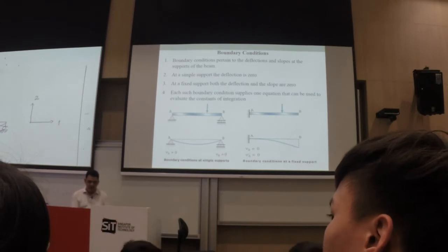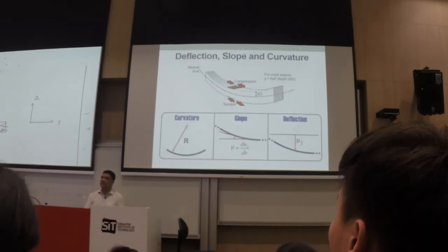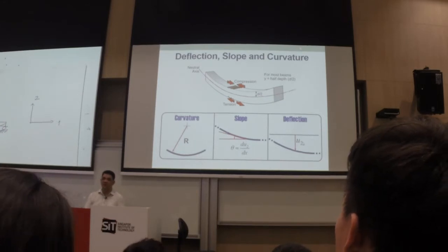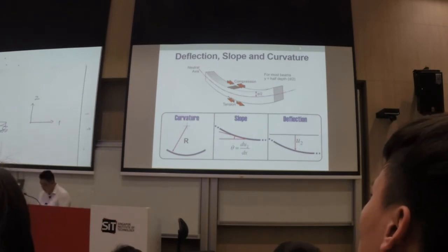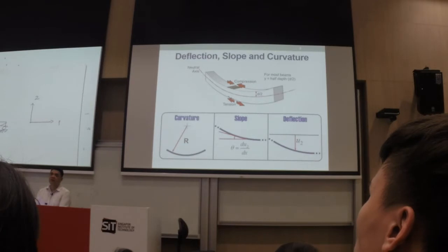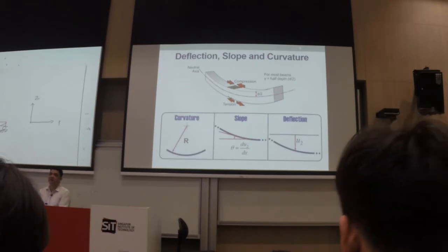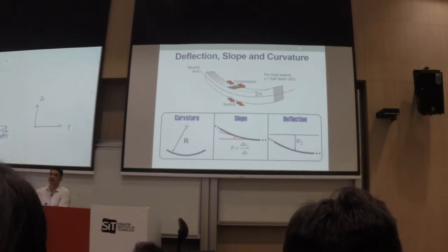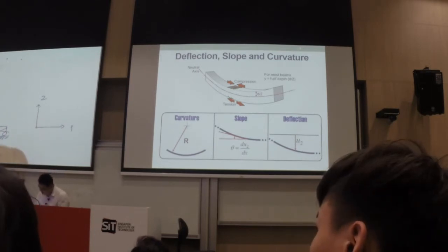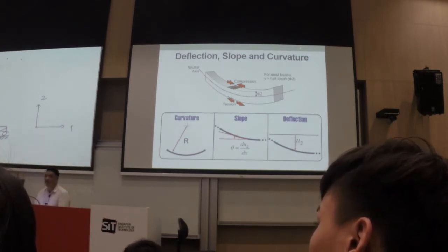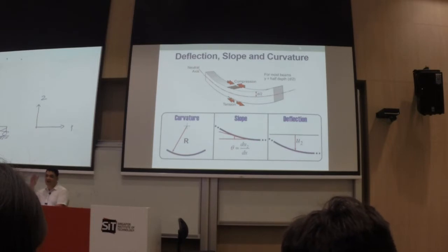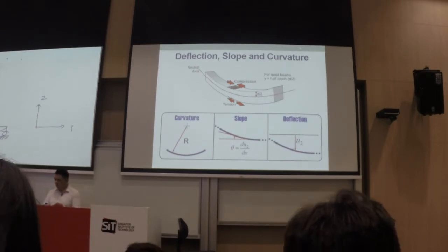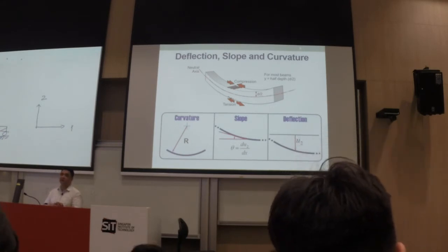Now, if I just go back one slide, we have here to consider a slope and deflection. So, if this one is going to bend, there will be a slope. Normally, we define this as an angle theta. So we have here angle theta, and of course, somewhere here you have your deflection U2. Right? So we have now two parameters: theta and that displacement U2.